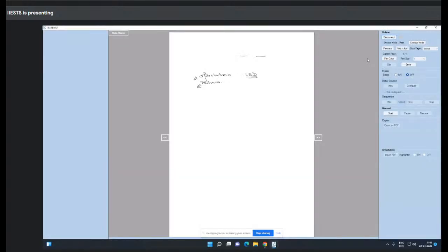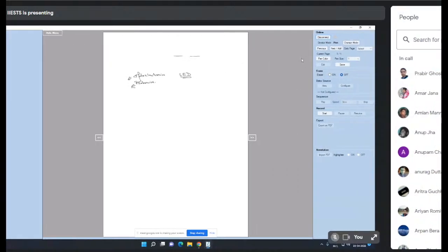And whenever you do this, you have to compromise with the bandwidth. When it comes in the optical domain, the bandwidth is very, very high. And when it comes to the electrical domain, then the bandwidth becomes very small. So this is one of the major constraints of today's optoelectronic technology, which is used in optical communication. Frequent changing from optical domain and coming to electrical domain, using all these optoelectronic devices make the systems.